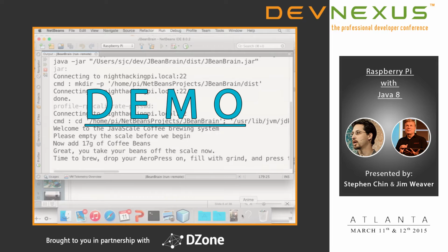But if you look closely at these cards, I'll pass one on each side. Just try to make sure it makes it back so I have a full deck. If you hold it up to the light, you can actually slightly see the RFID tag inside of it. So it's got a MIFARE Ultralight RFID tag. And I'm using a PN532 chip inside of the hat to pick up which cards are dropped in. So when you drop a card into the hat, it's picked up by the RFID reader. It looks up in a properties file according to the ID which card it is, and then returns that to a program.